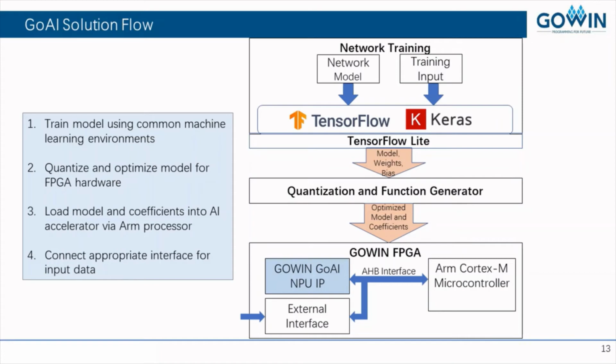It generates the FPGA bitstream or FPGA firmware that holds the hardware architecture for, in this case, image sensor input to the NPU and MCU architecture with the front end buffer. And then it'll also strip the weight and bias coefficients that will get stored in SPI flash, and then it will load all these to the board.